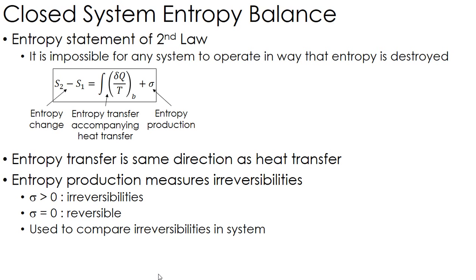Okay. Now, this entropy production is, again, the measure of the irreversibilities. Okay. The actual value, again, we don't have a strong idea. There's not a strong physical correlation between entropy and the physical world. However, it's useful in comparison. So say you've got a power cycle, you can do each process in the power cycle, find sigma for each process, and from that figure out which device is the most irreversible, and fixate on that and try to improve that performance. It gives you a place where you can devote time to make better, because as that approaches 0, the better your performance is going to be.